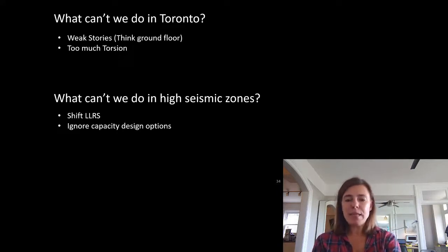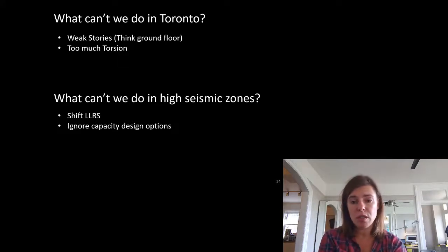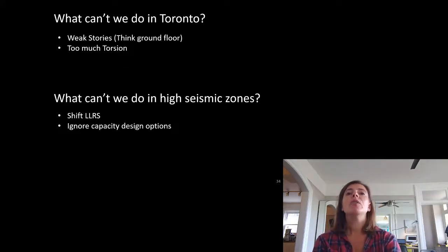But seismic, or earthquakes, is one of our lateral loads that actually has some heavy limitations on what we can and can't do. And it changes depending on where you are. Toronto is not a high seismic zone. What we can't do is have a weak story.